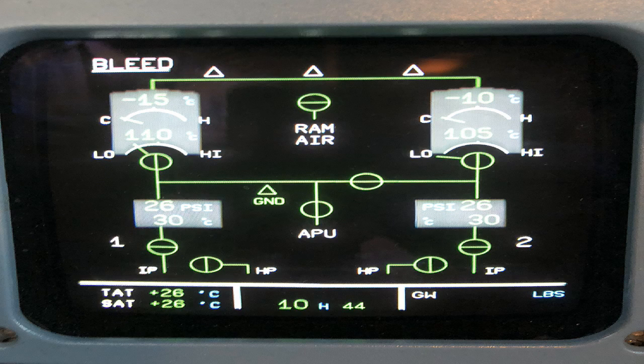And remember what I said, it's important to make sure the BMC is running, because it's picking up the signals from your pressure transducers and temperature sensors. If something is not working properly, then what's going to happen? Garbage in, garbage out. The garbage in may have been fine, but once it got through that BMC, there could be a wrong signal sent eventually to the Ecam. So it's important that it's maintained, and doing these tests makes sure that the BMC is running correctly, basically for its own self.